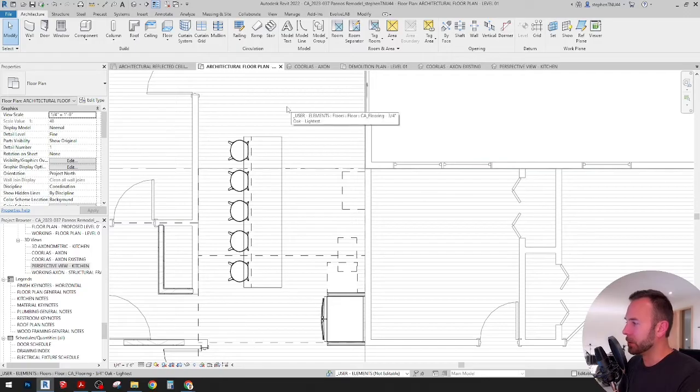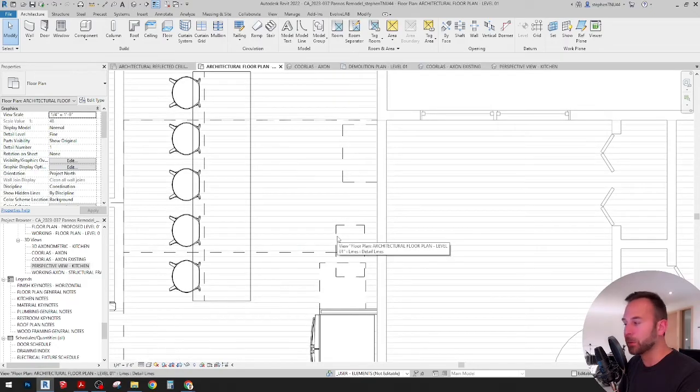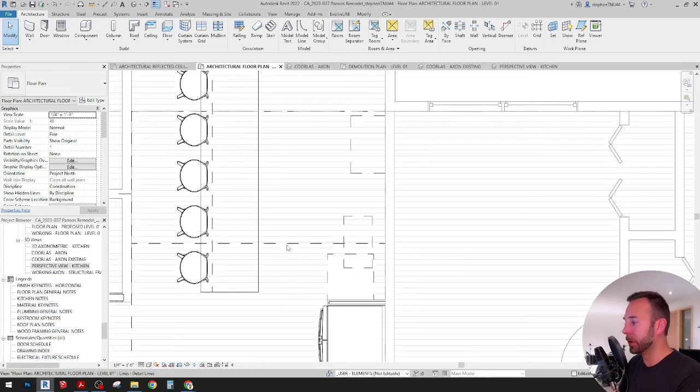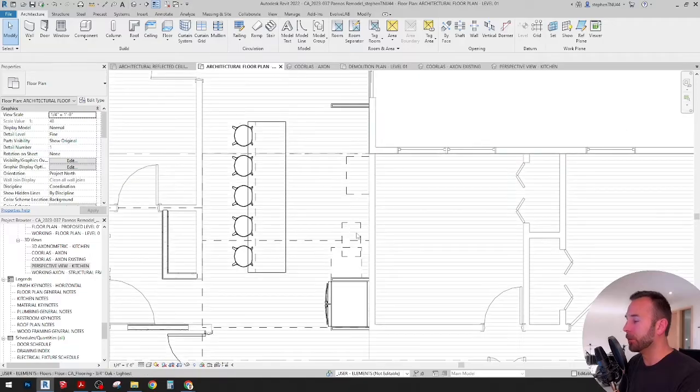You'll see it's basically just a game of division, seeing what fits. Using some standard widths. Cabinets typically come on 3-inch increments, so things like the sink, your oven or range, all those are going to have kind of preset dimensions that you're going to have to work around. And if there's anything like these beams in the ceiling that are cutting across, that's certainly going to inform where you can start placing some of these items.